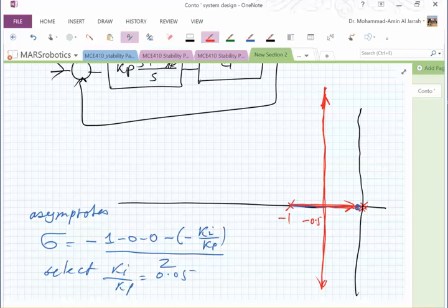Now, how will the root locus look? Some of you would say the root locus will go like this, right? Well, I'll tell you, because this is very close, the distance from this pole to the 0 is very far compared with the location here. These two roots might go like this, and one root here, and then one comes and meets this root here, and then they split along this asymptote.